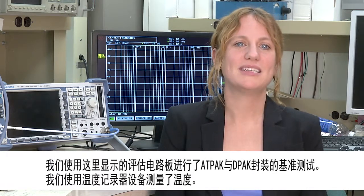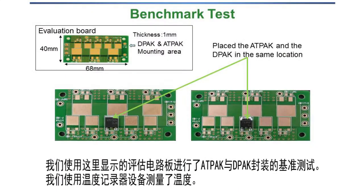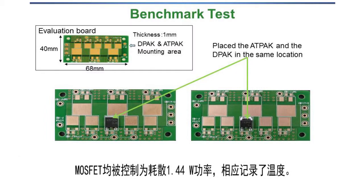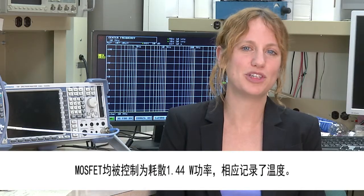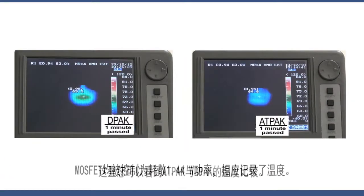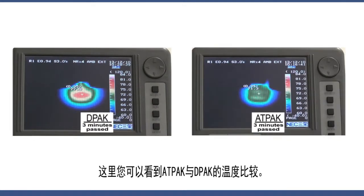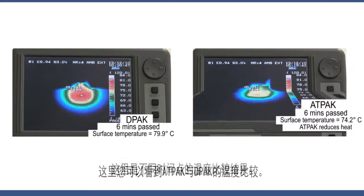We conducted a benchmark test between our Atpak and the D-Pak using the evaluation board shown. We measured the temperatures using thermograph equipment. We ignored the impact of the board on the heatsink since we mounted the Atpak and the D-Pak on the same position on the evaluation board. The MOSFETs were both controlled to dissipate 1.44 watts and the temperatures were recorded. Here you can see the temperature comparison of the Atpak versus the D-Pak. Here are the results over time.